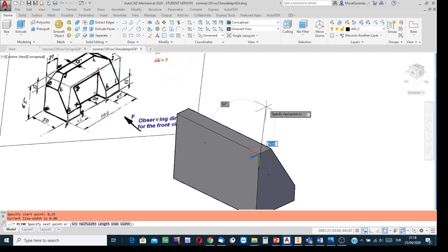And the ending point corresponds to the image of MD. Yes, for this point relative to the origin, it is at that corner. The abscissa value is positive 20. Click on the comma key. Ordinate value, yes, 15. Delta y is 15. But since this measurement is in the negative sense of the y-axis, 15 must be written as negative. Minus 15. It is important. And then press enter.